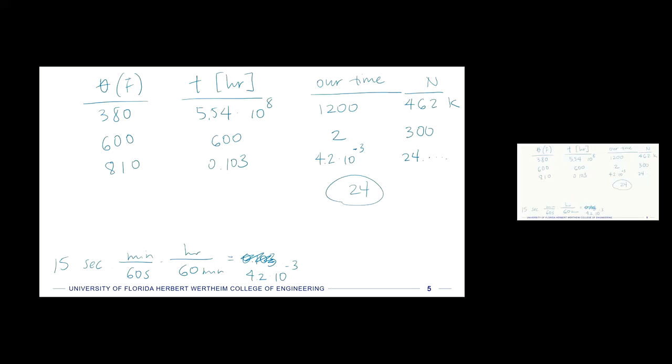And so this is just a very kind of back of the envelope way of calculating this, right? Because we only have one curve, we don't know what happens truly at these other temperatures, at other stress levels. This is all the information that we're given, so this is the best that we can do. This does not take into consideration any sort of accumulative creep strain, right?